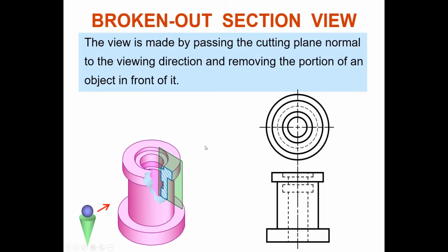So it means in your orthographic drawing, you do hatching like this. By hand. This one not by ruler, by hand. And straight. And like this. Then, that portion, that region, only you do section line. Clear? This is what we call broken out section. Sometimes the drawing can be like this. You don't have to do full section or half sectioning, because only this region you show people so that they clearly understand all the rest of it. Clear that, class? You can do this. If you do this, it's much better actually. Really, you follow standard.